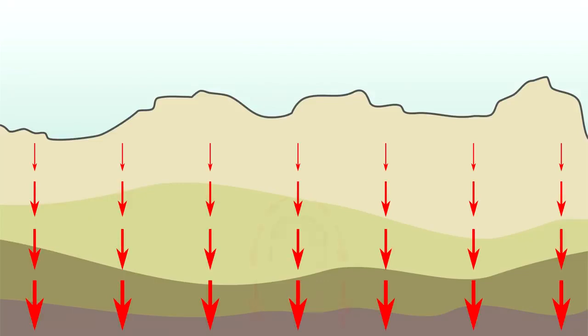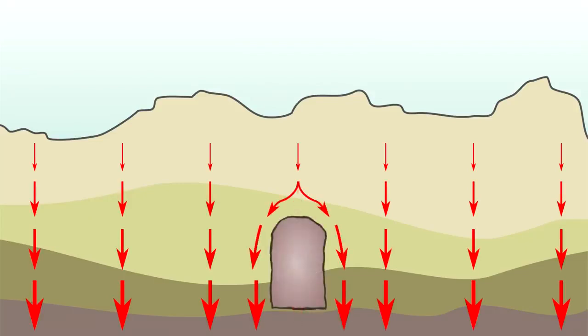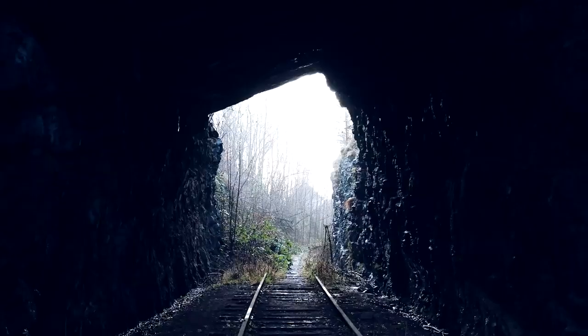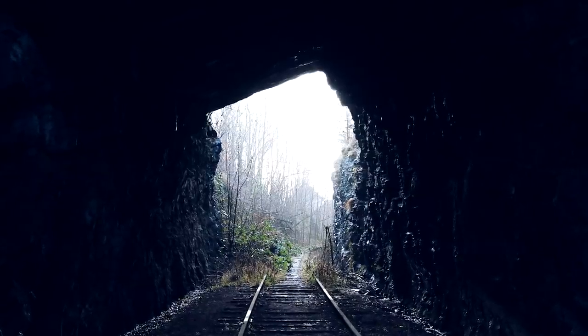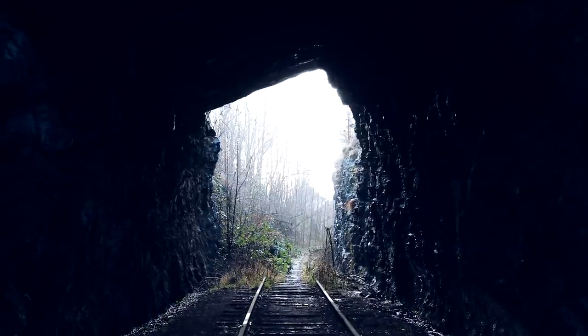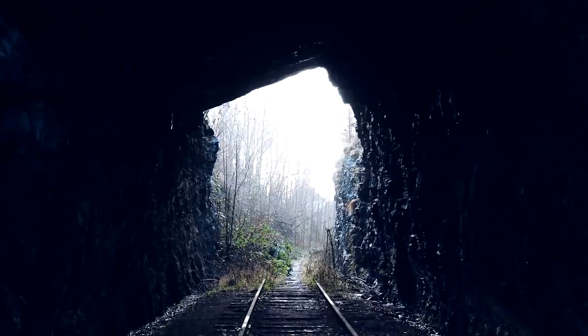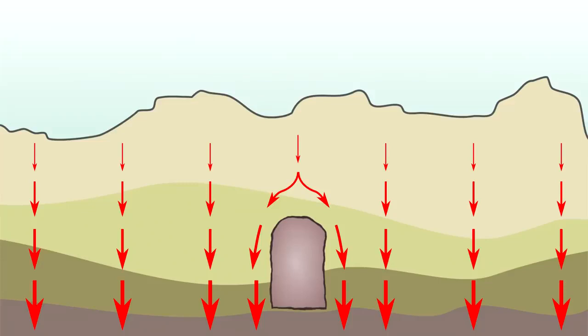Building a horizontal passageway, or a tunnel, through this material interrupts the flow of these compressive forces. Just like if you remove a column from a building, excavating a tunnel takes away the support from the material above. Where you once had compression throughout the subsurface, now you've created a zone of tensile stress, where the material above the tunnel is trying to pull away from itself. Many materials react differently to tension than they do to compression, and soil and rock are no different.